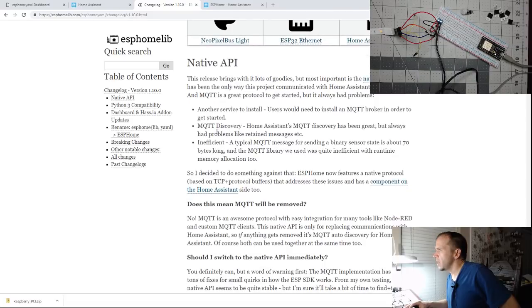Yeah, they were talking about how it's inefficient with MQTT discovery. And this was one of the problems. I don't like to use MQTT discovery. Same thing with Tasmota, because sometimes I'm testing stuff or I don't want all the relays because I just want the temperatures. I may be using, say, a Sonoff Basic, and I just want the temperature sensor, or if I'm using an S31 and I just want the power and I don't want to actually turn the device off. I don't want the relay in Home Assistant. I like to control everything myself, so that's why I don't like to use the MQTT Discovery.